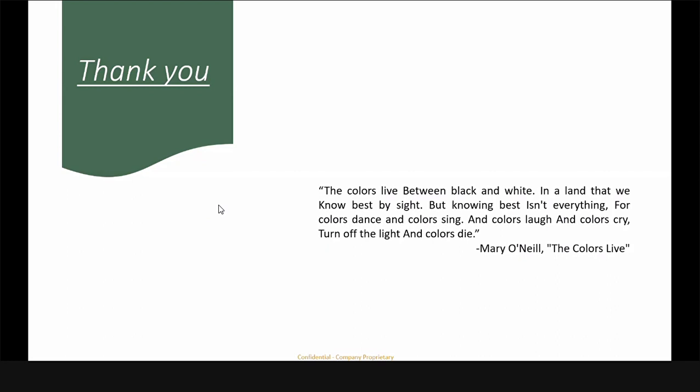Over white over black means the first measurement is with the white tile placed on the sample port, and the second measurement is with a black card or black sphere placed on the sample port. Based on that, it checks the light blocking ability of the fabric, which is also called how blackout the fabric is. Yes, this is the total transmission method for that.